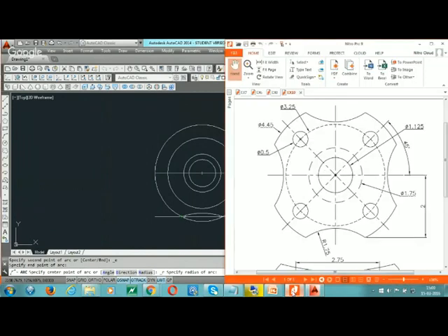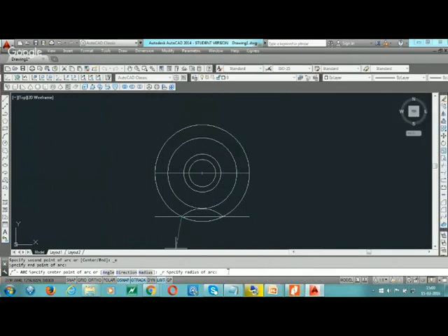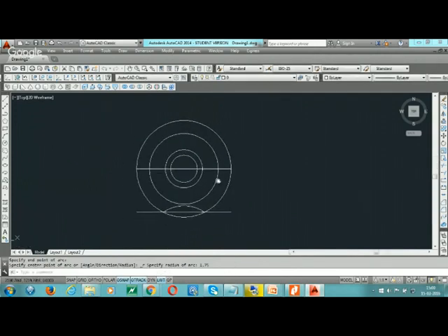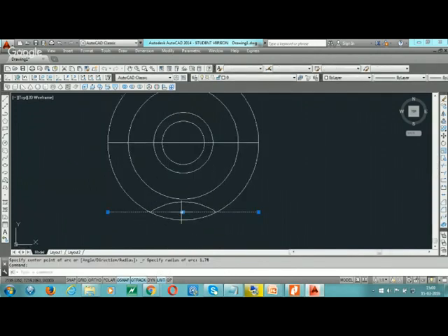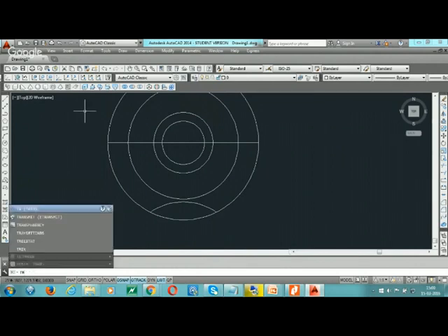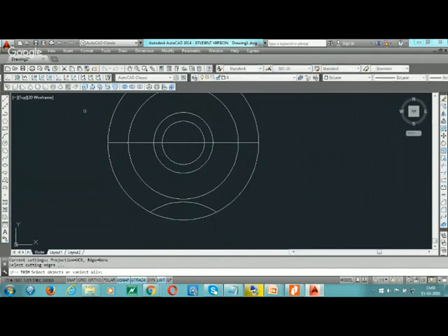Go and check the dia is 1.75. Now write the radius 1.75 and enter. After that, trim. First select and erase the line, and go to the trim command, TR double and TR enter, select all.